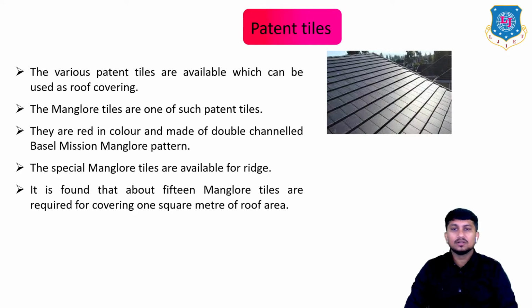Special Mangalore tiles are available for the ridge. It is found that about 15 Mangalore tiles are required for covering 1 square meter of roof area. In this way you can easily calculate the number of tiles required for your construction.